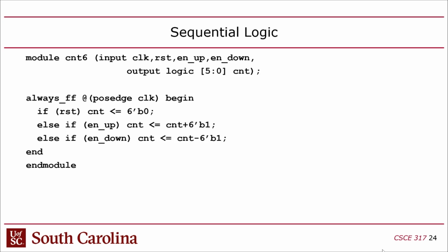Software would have to use a slow protocol for that to work, because otherwise it would be difficult for software to keep up with a protocol that requires cycle accuracy. In SPI, the interfaces have to keep up with the clock cycle, so it's difficult for software to guarantee that. So bit banging is kind of rare. People do it, mostly hobbyists, but usually whenever you have one of these bus interfaces, it's done in hardware.